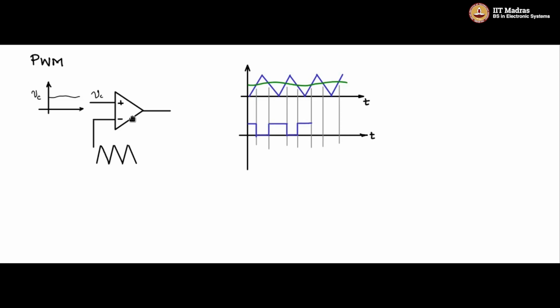It depends upon what type of op-amp you are using. If you are using a bipolar op-amp, then it will go positive, minus, like that. So let us say that we are having a unipolar op-amp with only VCC, VSS grounded. Therefore, you will see the output going positive to 0 in this fashion, thereby giving a pulse width modulated waveform. If you call this VA, this would be VA.